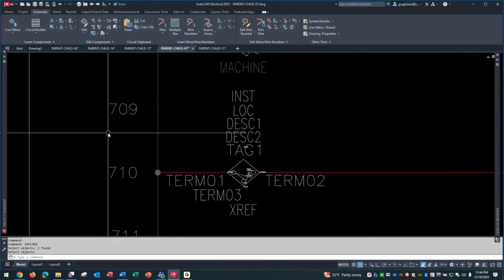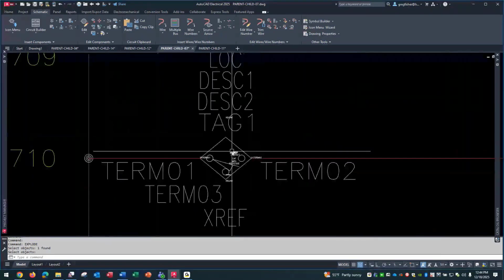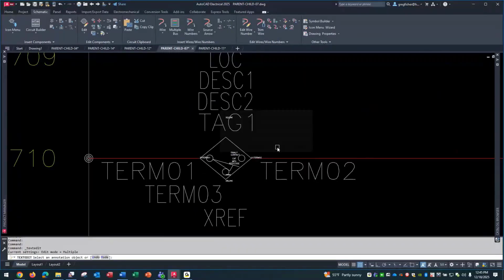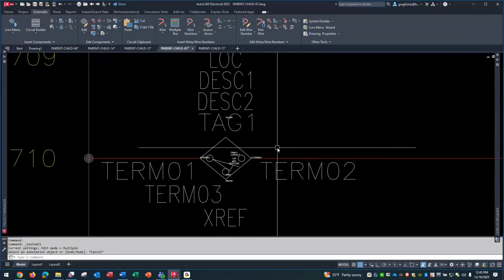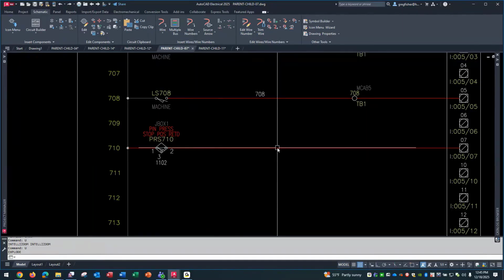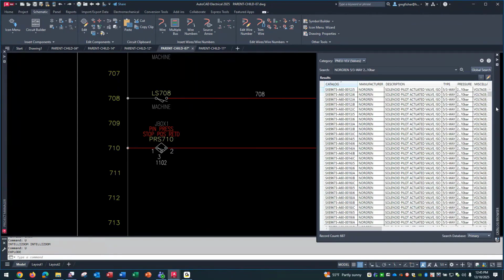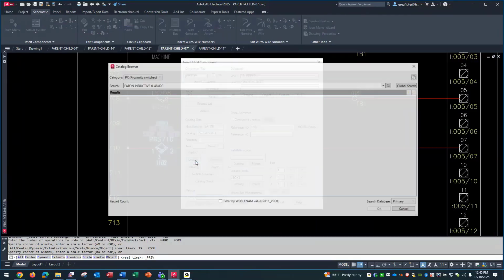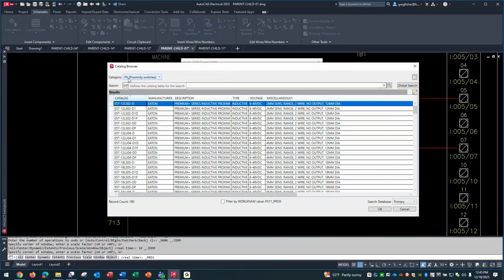Normal symbol. And again, it's just tied to the table that you want to point to when you hit the lookup button. Can't stress that enough. In the symbol builder, make sure your table is pointing, through that family attribute, to the proper table. And again, some of you probably know this already, but it's all about when you hit that lookup button, you want to make sure that it goes to the proper category, which is a table in the catalog database.